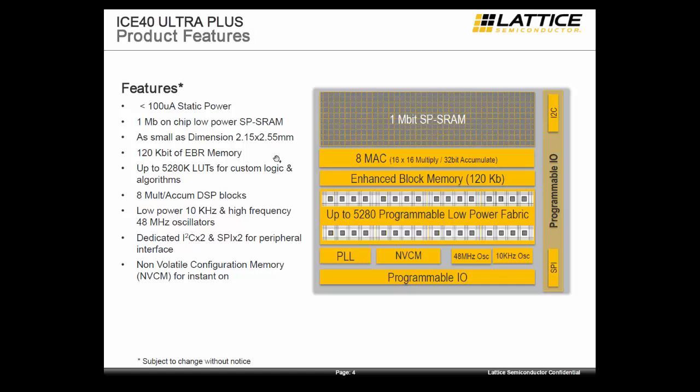So the device has an SRAM based architecture where the function and the configuration is booted up from SRAM. However, upon power up, if the NVCM memory is populated with a configuration, we allow that configuration to be self-downloaded into the device. So multiple ways of bringing up this device. So here's a quick block diagram of the product features.